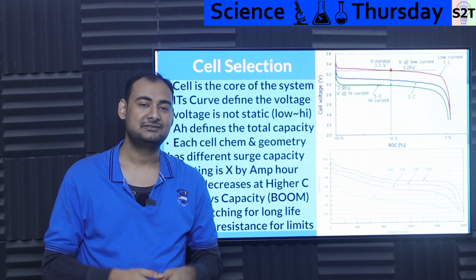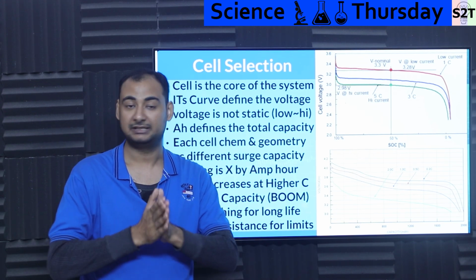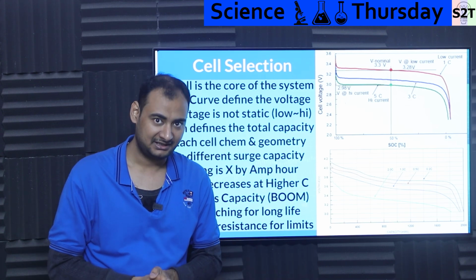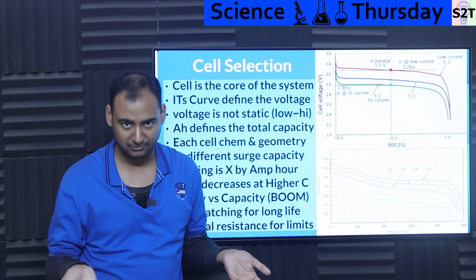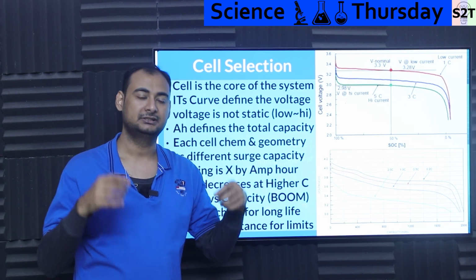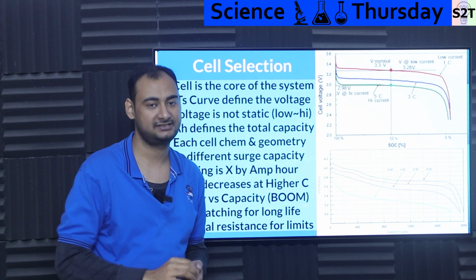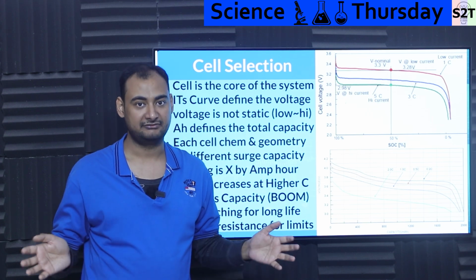And again, any company that gives you a long warranty on cells, like in India, there are a lot of new manufacturers coming online. They are still buying cells, but how are they giving you a 15 year warranty? Well, they are doing cell matching. What does that mean? That's simply the same curves. They can be plotted in equipment that puts load on the cell at different temperatures and logs everything, meaning you can figure out the internal resistance. And because it's a chemical engine, all cells are different.